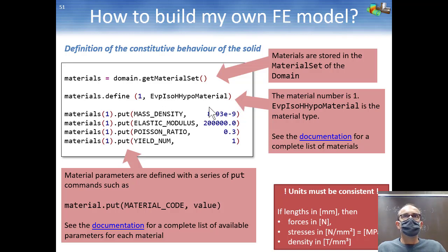So there are many materials, many behaviors, and this is the simplest nonlinear one. It's an elastic one, and once the yield stress is reached, there is some plasticity. The plasticity is isotropic, and the hardening of the material is linear. But there are many, many other ways to define more realistic materials. But of course, in your model, just start with this material, because it should work.